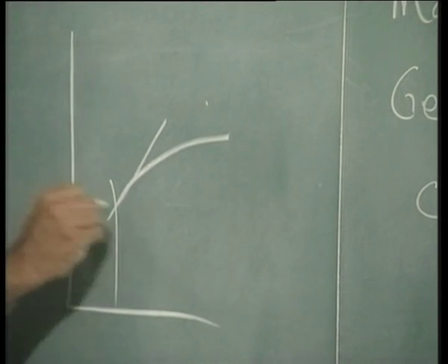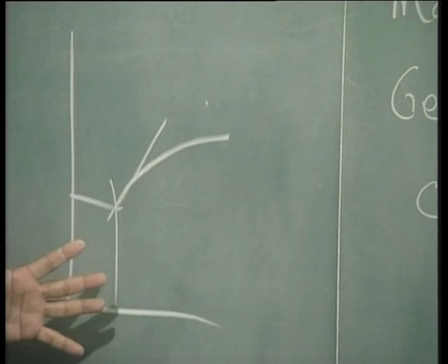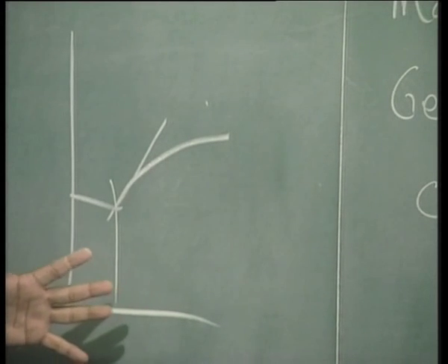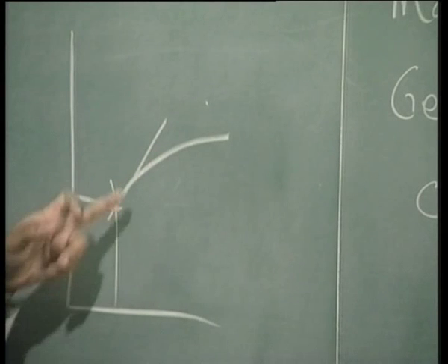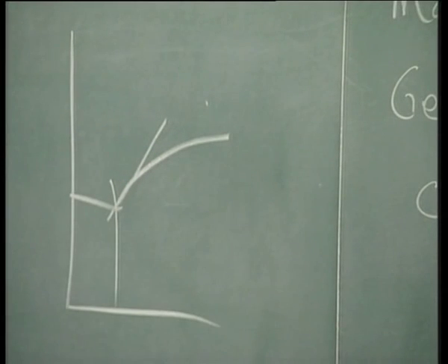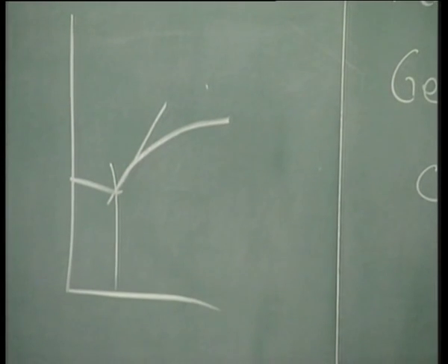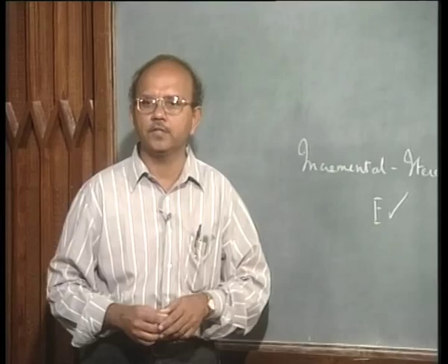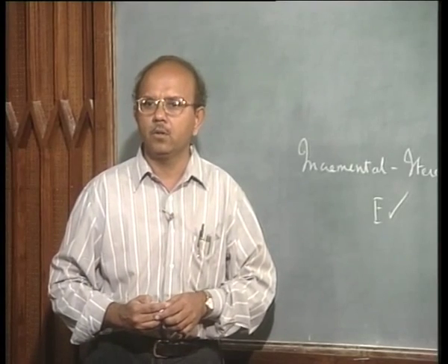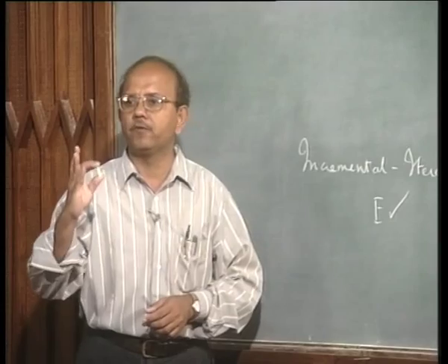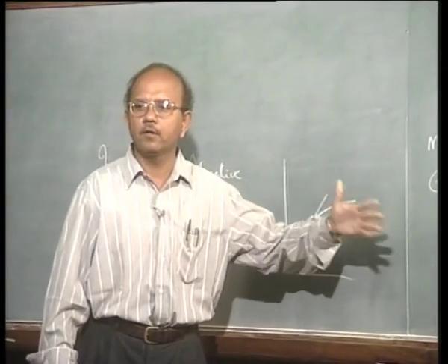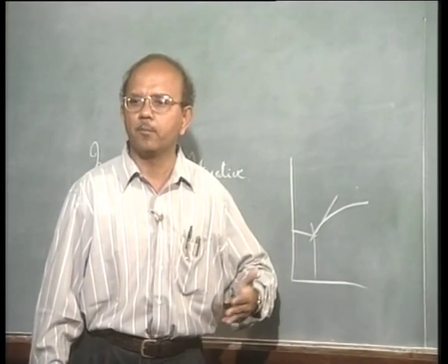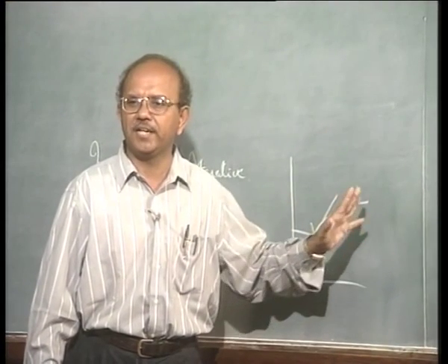At this point, let's look at this as a load deflection curve for the time being. The slope of the curve is what I have taken, from which you can easily work out the tangent and hence the stiffness. Now what happens, like our friend said, if I divide it into a number of linear parts? I just exaggerated that.